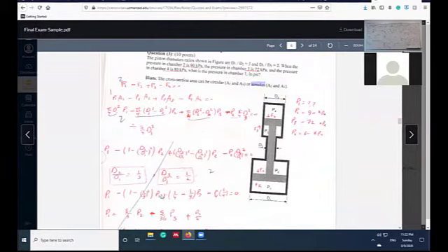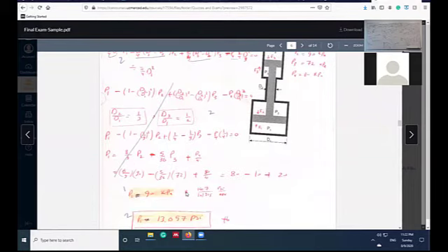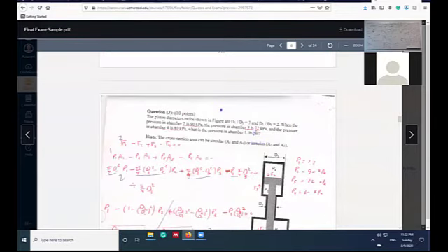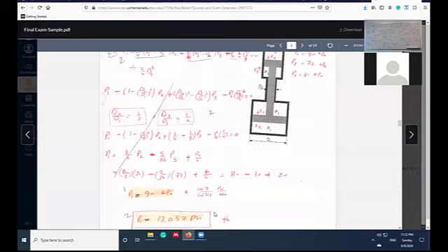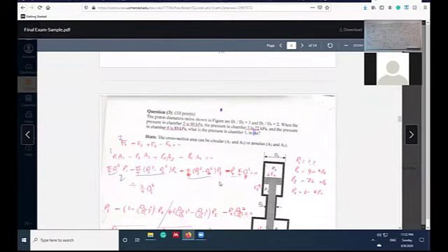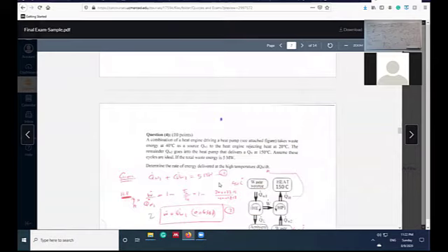So you can get just one simple equation in all the pressures and area ratios or diameter ratios squared. So you can get just P1 in terms of the rest. Substitute the pressures, you get P1. You can convert it to anything he wants. He wanted it in PSI, so convert it from Pascal to PSI. Is it hard, guys? Easy. You will see it in the exam.